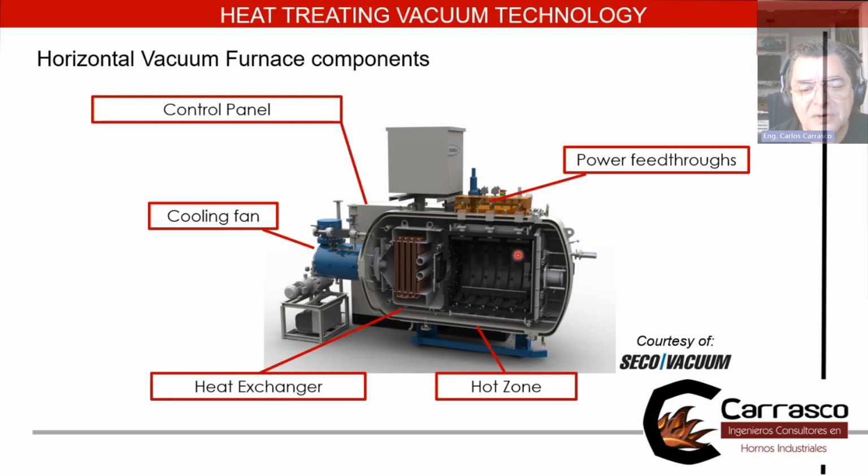Once the load is at temperature and all the soaking is happening, this furnace has a hatch in the back. It opens and the furnace is backfilled with nitrogen, most of the time with nitrogen at high pressure. The furnace, when it's open, is at 1 bar of pressure, atmospheric pressure. But when we close it, we can pressurize the furnace up to 6, 15, even 25 bars.